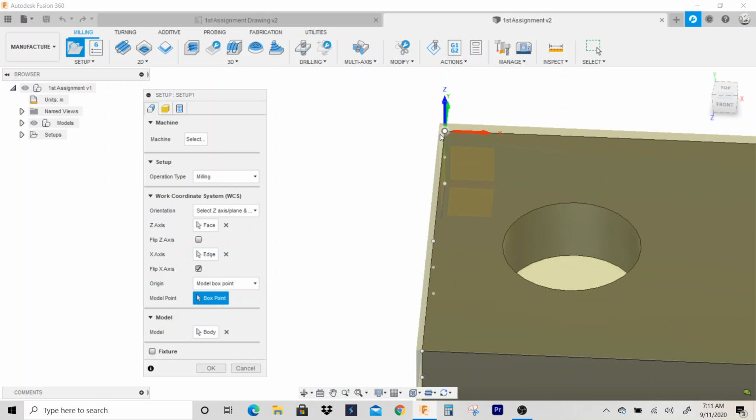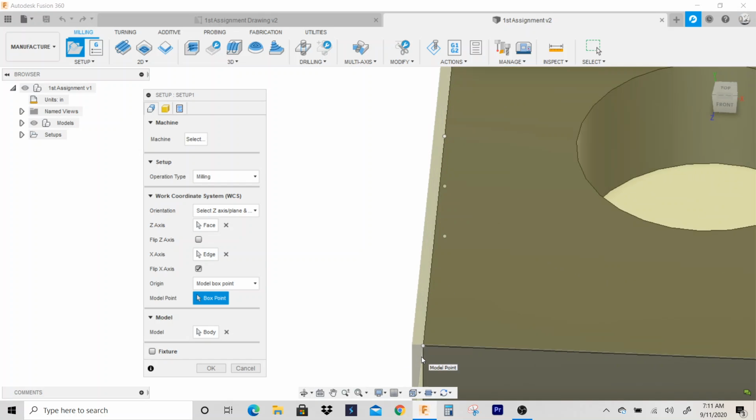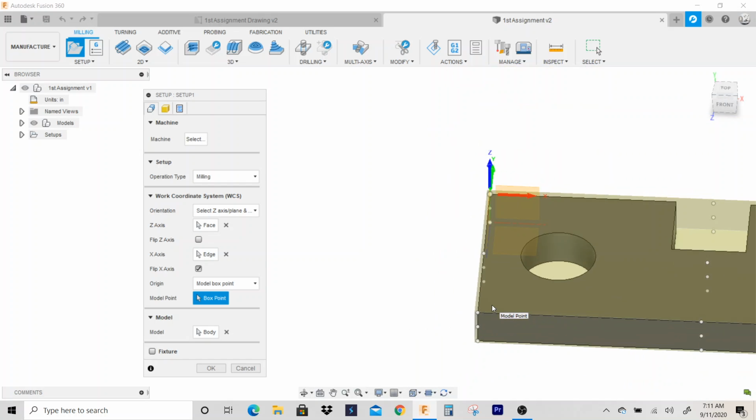But the pros of having it up here is the way that vises are made. Your fixed vise jaw is the most repeatable surface on the vise. Okay, you've got two gripping points. You have your moving jaw that you lock and unlock your part, and then you have your fixed jaw. Okay, for repeatability purposes, it's better to have your Y0 up there, but to keep the G-code simpler, it's better to have the point right here. So it's really just preference. Depends on what you're doing.